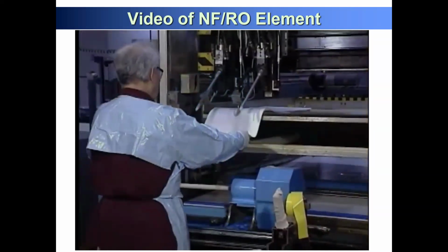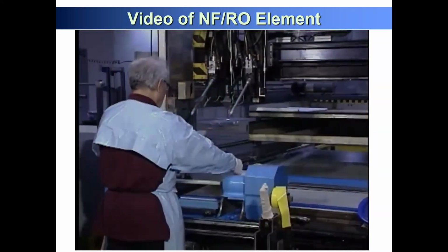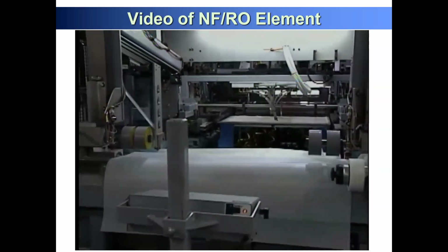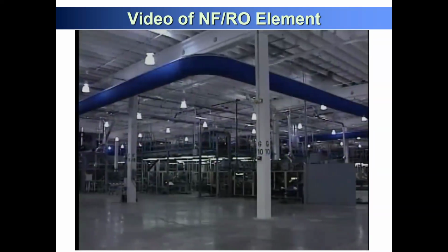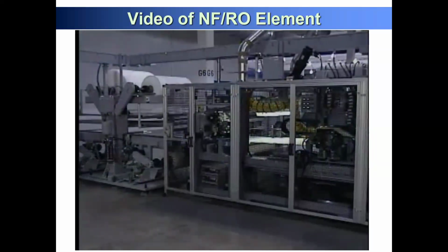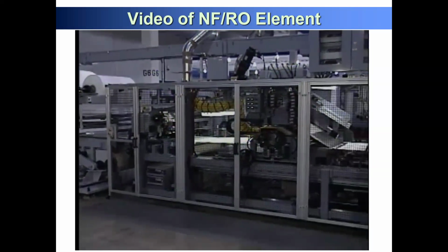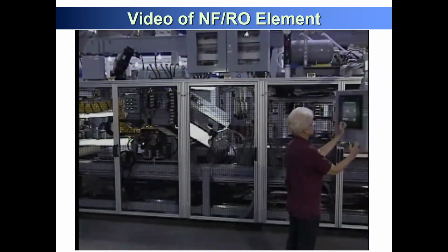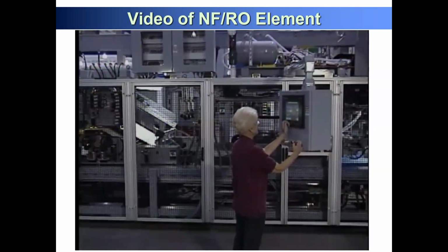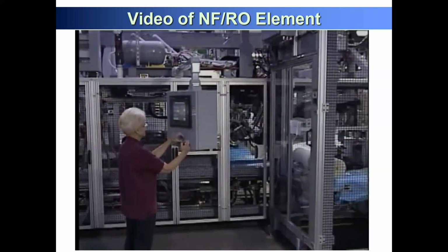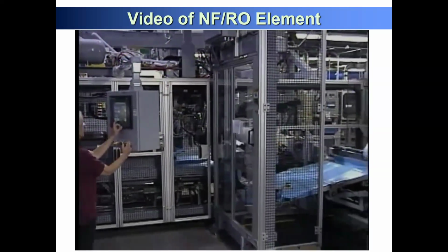A spiral wound membrane element can be fabricated manually or automatically. Dow uses custom-designed precision rolling equipment to automatically fabricate FilmTech elements because it allows for better, more consistent element performance. Sophisticated robotics for leaf construction and assembly ensure that every element is precisely built without membrane damage that often occurs during manual handling.